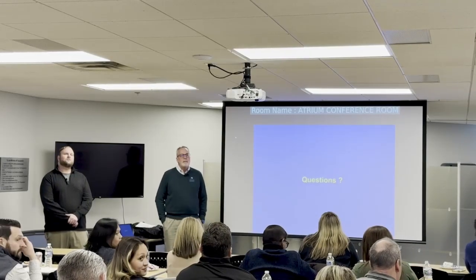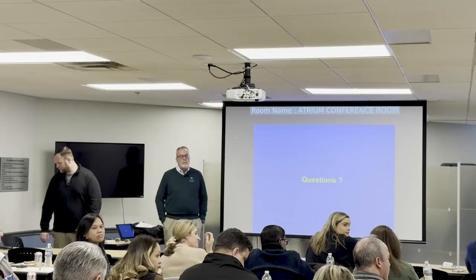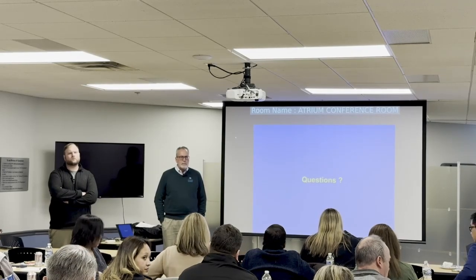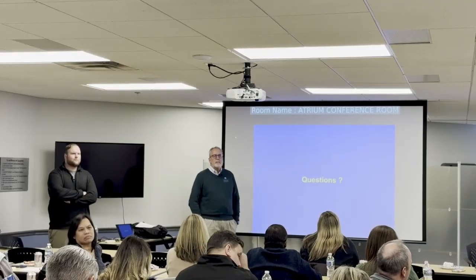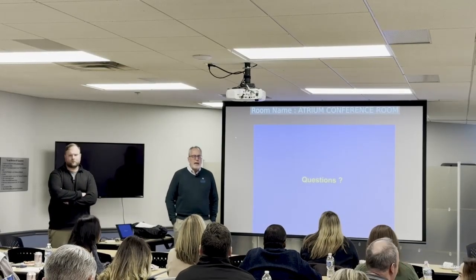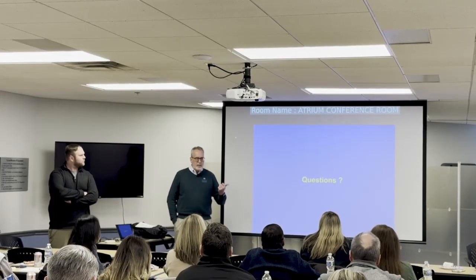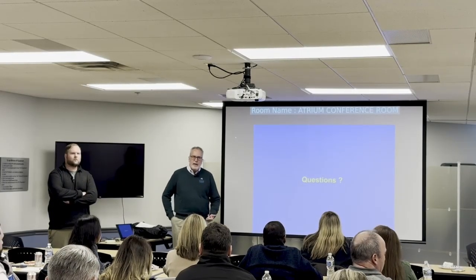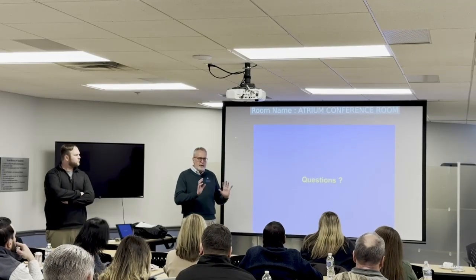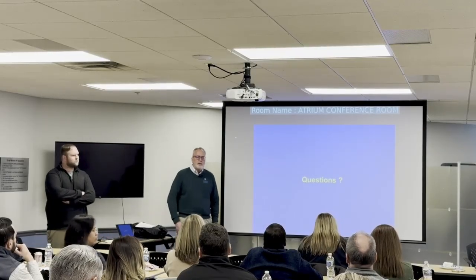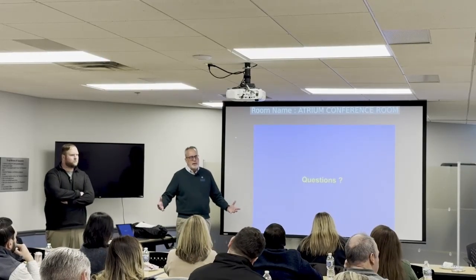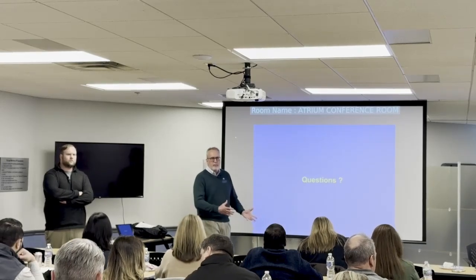Just a random question, if you could set the record straight from an environmental professional. If you know that you have a site that may need extra work, can you just go straight to a phase 2, or you have to have a phase 1, then go to a phase 2? I feel like sometimes I get that from my lenders, and I guess I just want you to say that. We can, but we don't know if we've got all the chemicals of concern and all the areas identified. So if we go out and we say, well, there was a tank over here, we can certainly go investigate that. We call that a limited subsurface investigation, but you just want to make sure that there's not other issues. Otherwise, you're not getting to that end point that you like.